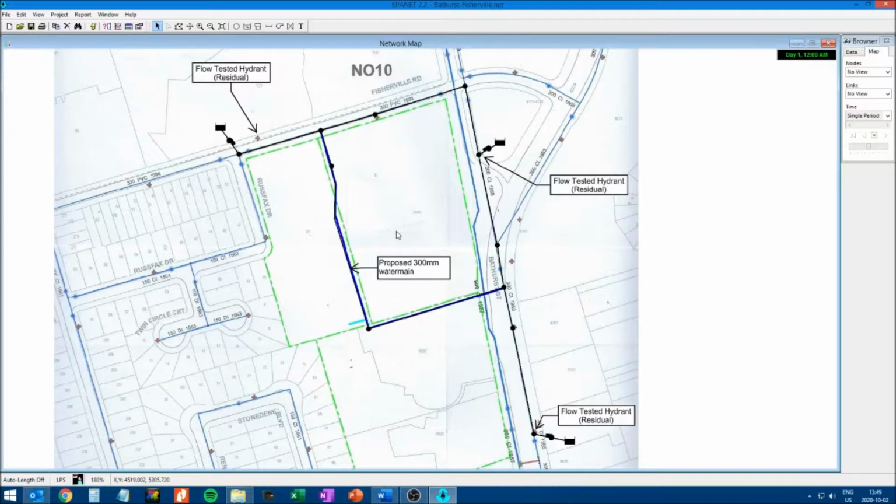And actually this value includes the fire flow value plus the maximum day demand. So our biggest value is 183.6 liters per second, and to make things a little bit simpler, we're going to just apply that demand at this node and this node, and make sure that this pipe can carry that flow